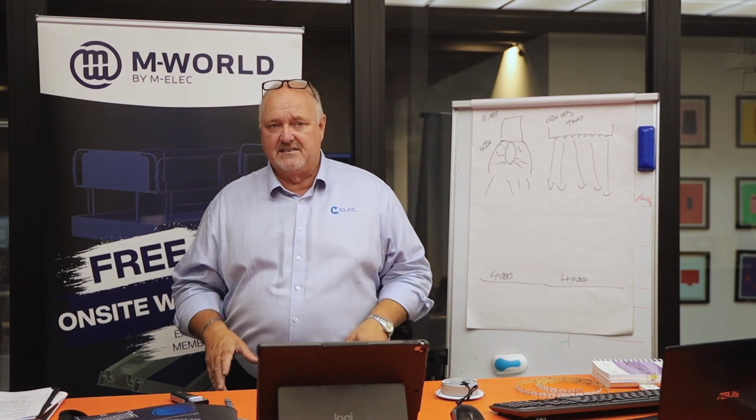IP68 is for being submerged in water, taking the pressure of that water around it. If I took a device that is IP68 and put it where I put an IP65 light, and put a jet of water on it, there's a good chance it will leak, because it's designed to take the pressure of being submerged, but not the pressure of jets of water. There's a big difference between the two.